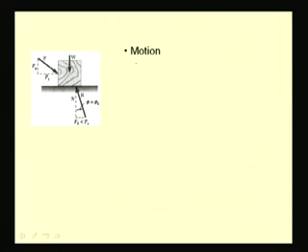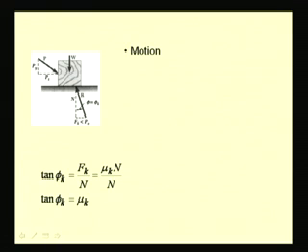And when the motion starts, we know that this reaction drops, that means its inclination comes down because the horizontal component of the force reduces and becomes the kinetic frictional force Fk, which is less than the applied horizontal force, and the angle of this resultant with the normal is equal to the angle of kinetic friction phi k.